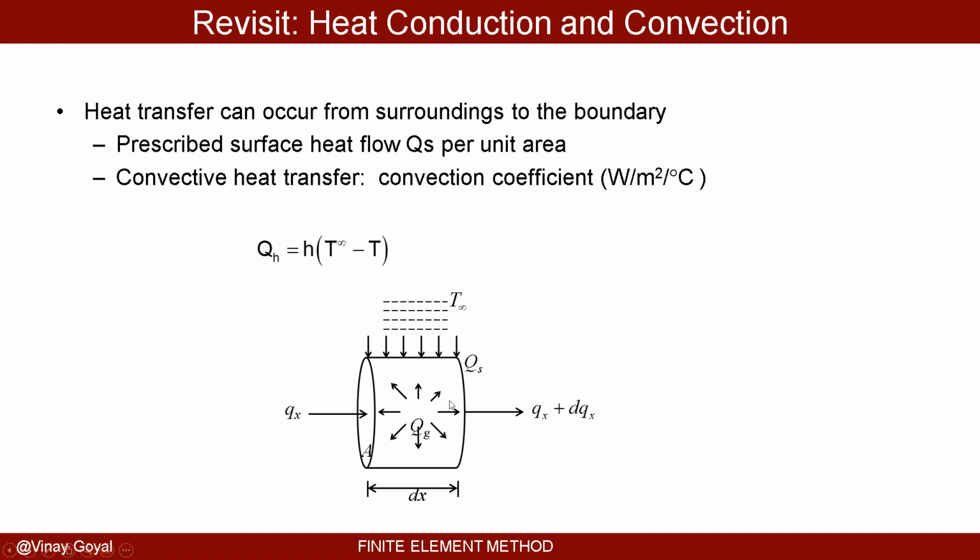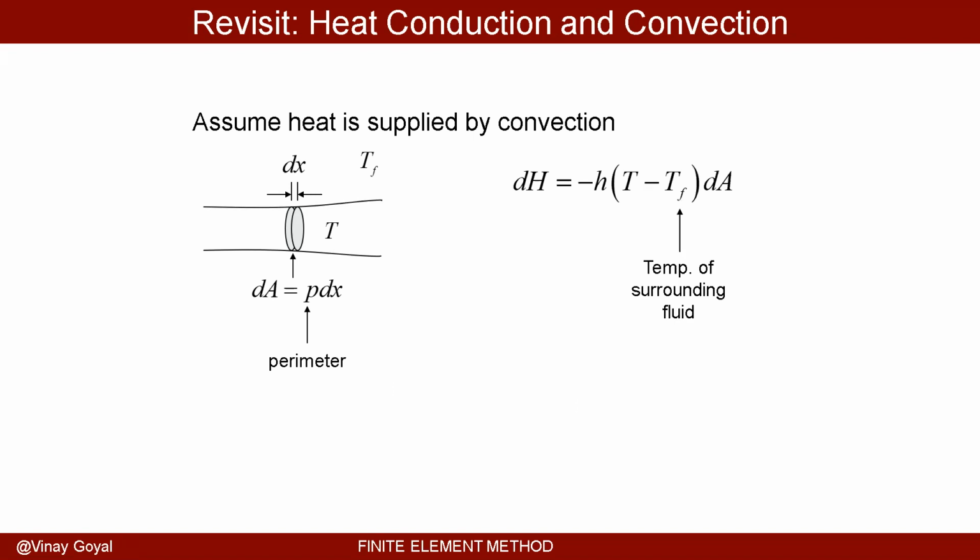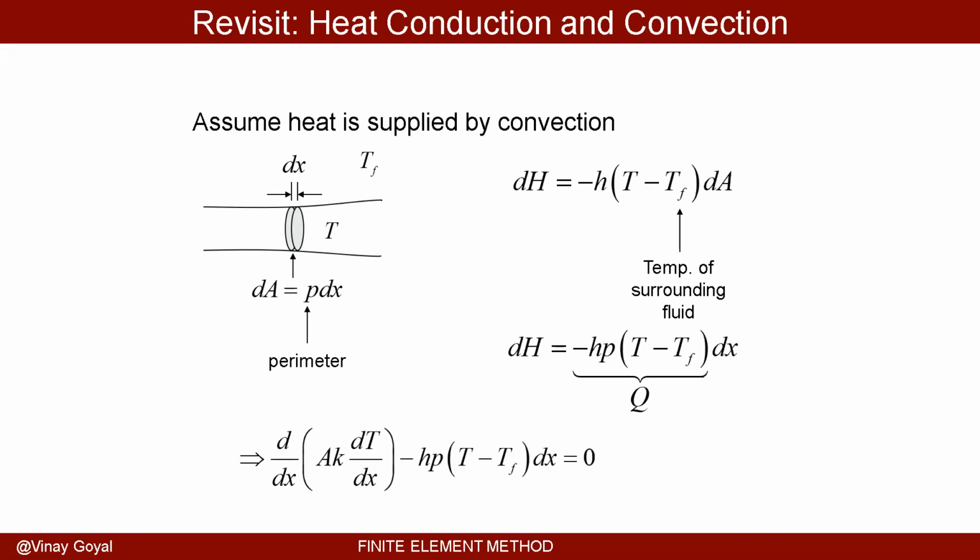So when you have a hot structure and you embed it in a flow that's a different temperature, you're going to have heat transfer, and that's given by the difference of T at the wall minus T of the medium, multiplied by the convective heat transfer coefficient, which is a measurement one could make. And it's hard to make, by the way. I already covered all this.